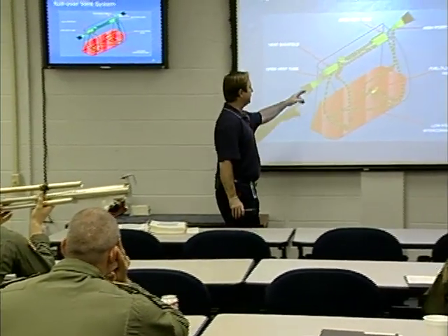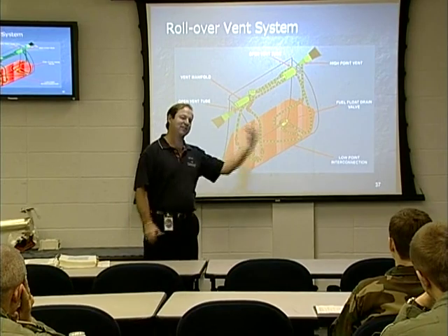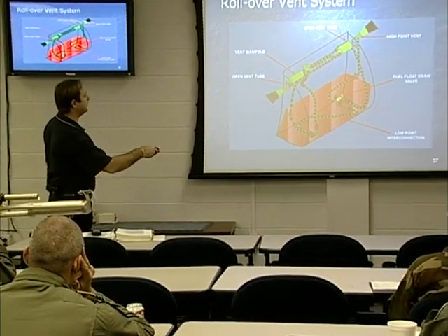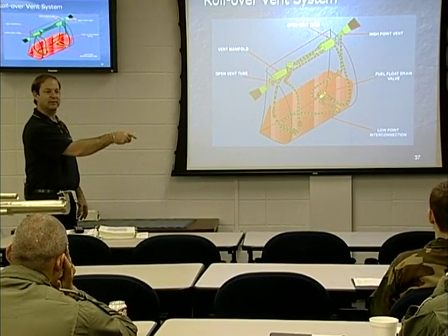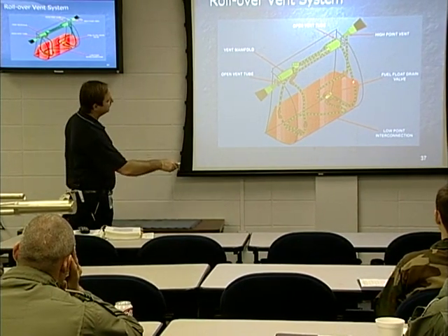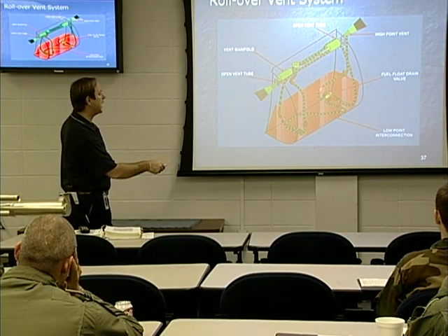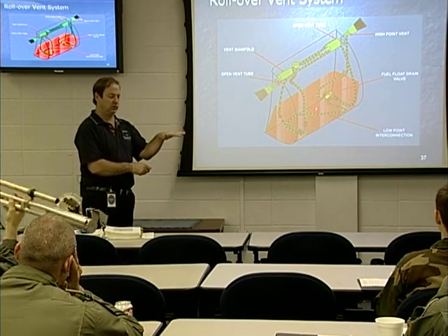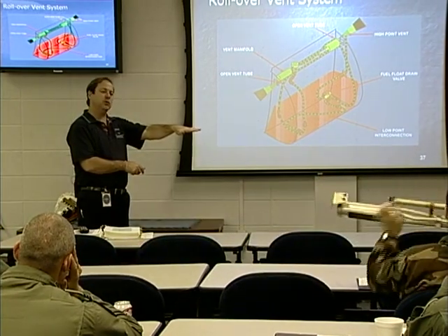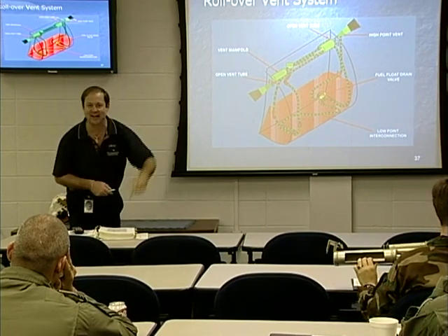Well, now, if this becomes the bottom of the tank, then the bottom of the tank now becomes the what of the tank? Top. And was the fuel all the way up to this very, very tippy top at the beginning? No. So in the rollover scenario, is the fuel going to make it all the way up to the very, very top now? No. And then as the aircraft continues to roll over, should that occur, the fuel is going to go through the path of least resistance, which was what? Back out the same way it came in.